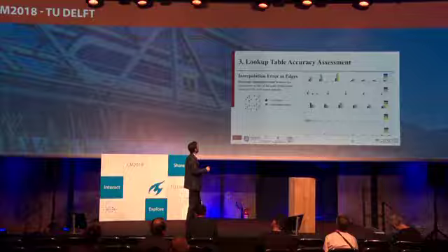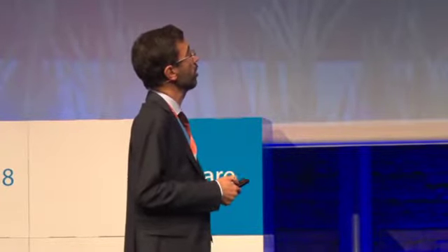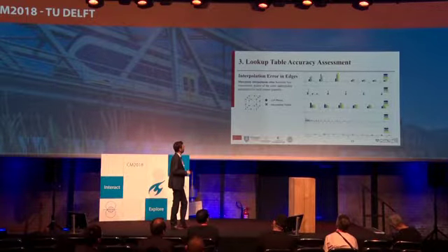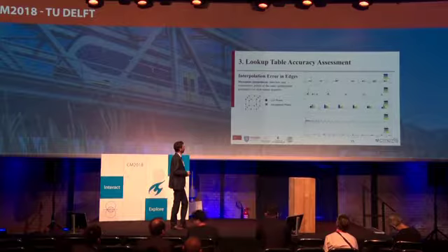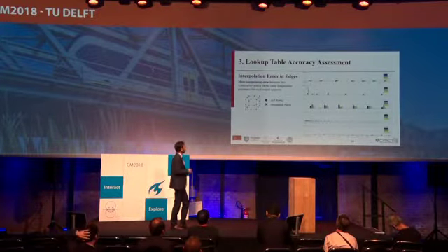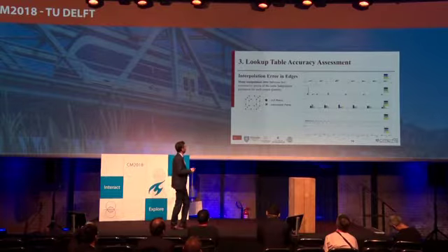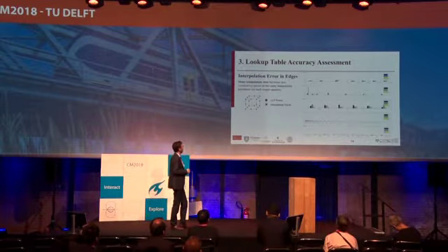Sometimes we have quite significant effects of these variables, suggesting that we probably need a better interpolation here, like having more points in the lookup tables. Whereas in other cases, like the magnitude of the non-dimensional creepage, this is much less critical. The previous one was for the maximum error, and this is for the average error over all edges in the cells.